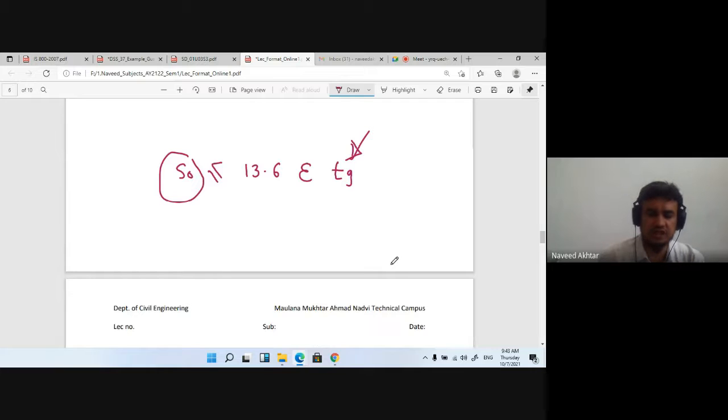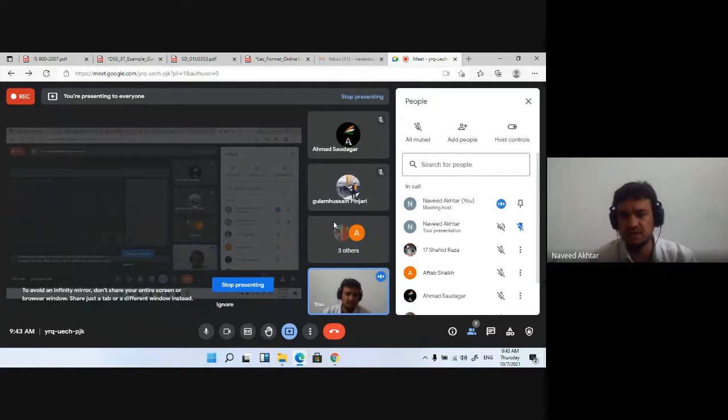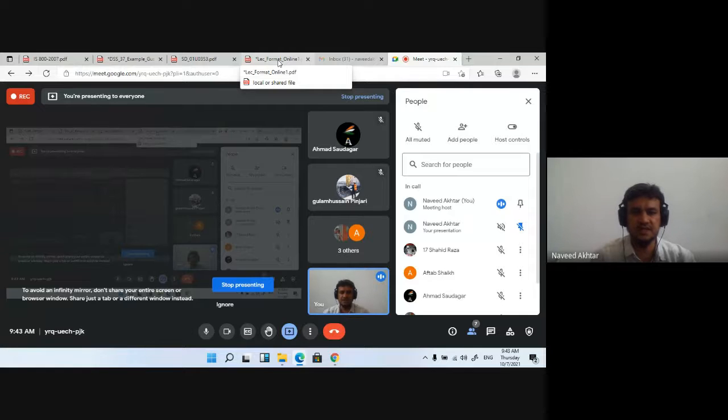Also, the thickness of flange should be less than the thickness of gusset material or base plate provided, that is 16 mm, and the thickness of flange is 11.6 mm. So our design is complete here, and these checks are given in the code. Likewise, we complete all the design calculation for the gusset plate design. If you have any question, you can ask me. Otherwise, we proceed. Now we see the moment resistance base.